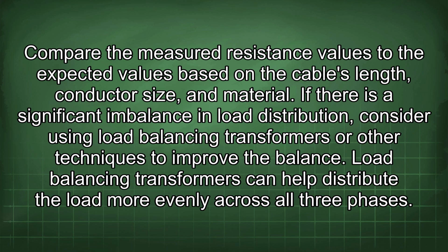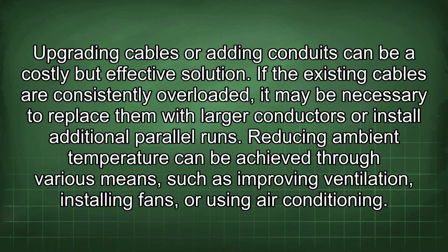If there is a significant imbalance in load distribution, consider using load balancing transformers or other techniques to improve the balance. Load balancing transformers can help distribute the load more evenly across all three phases. Upgrading cables or adding conduits can be a costly but effective solution.